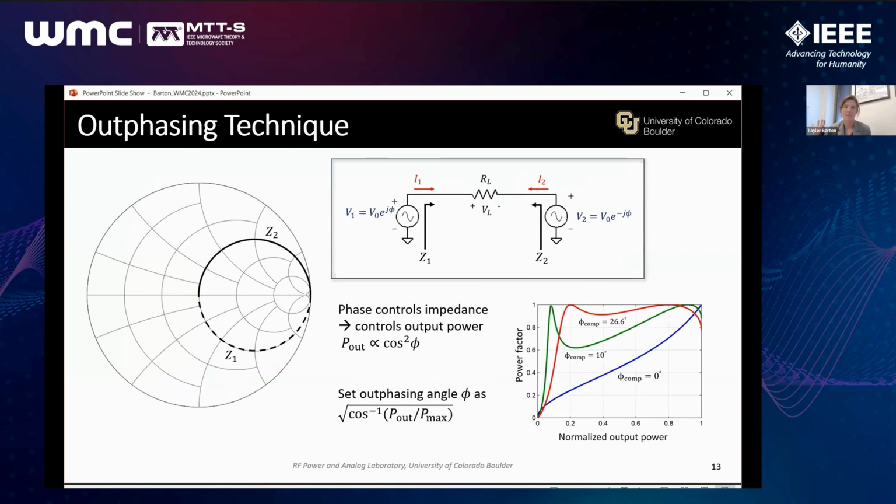The big picture concept of outphasing is that you have two voltage sources driving a differential load. And as you change the relative phase of the two drives, you get different effective impedances seen into the two PAs. So if you drive the two equally but out of phase, you get the maximum current through the resistor, which gives a small effective resistance. If you drive them the same on either side, then you get effectively an open circuit between the two nodes. And any combination in between can give you an impedance between R/2 and infinite load impedance.